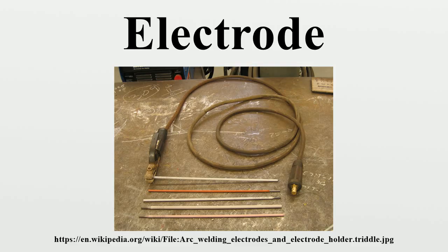Welding electrodes. In arc welding, an electrode is used to conduct current through a workpiece to fuse two pieces together. Depending upon the process, the electrode is either consumable, in the case of gas metal arc welding or shielded metal arc welding, or non-consumable, such as in gas tungsten arc welding. For a direct current system, the weld rod or stick may be a cathode for a filling type weld or an anode for other welding processes. For an alternating current arc welder, the welding electrode would not be considered an anode or cathode.